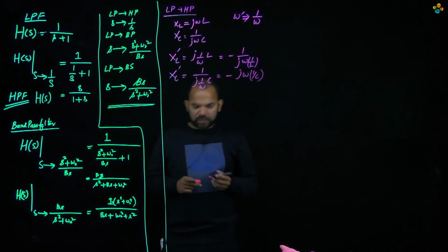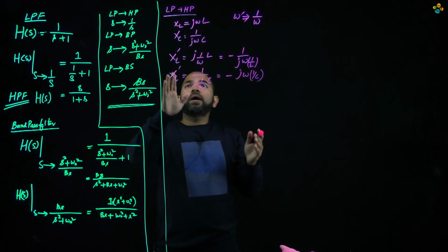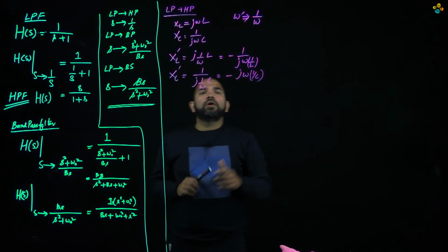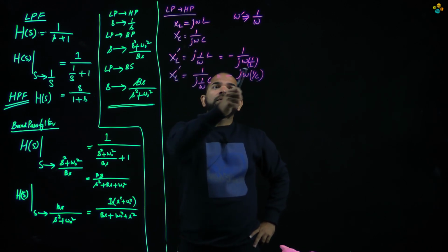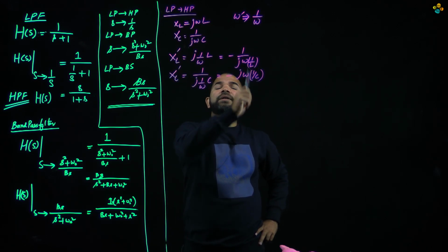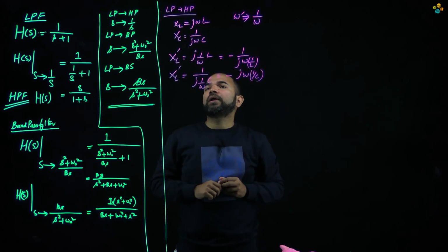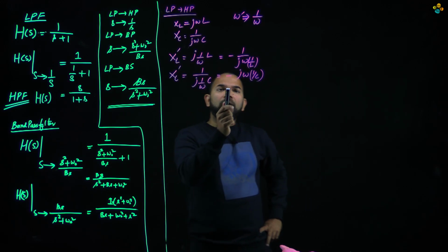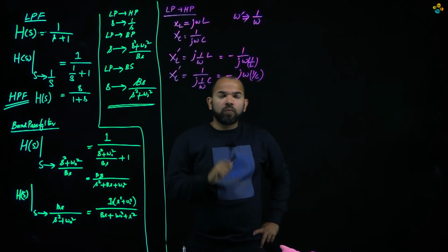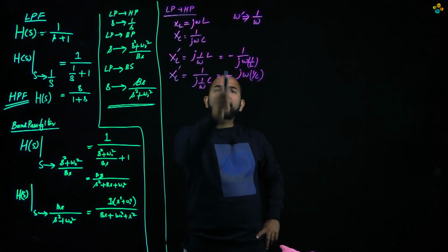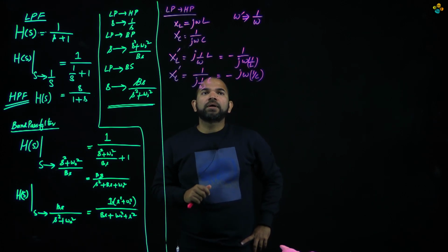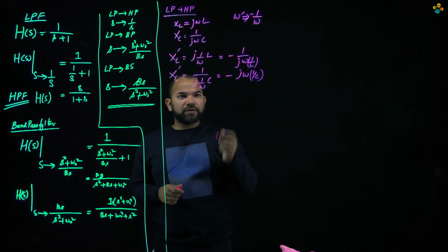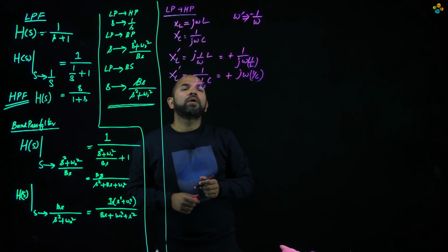So what we have seen, if we have to use this transformation, the inductance is gonna be replaced with the equivalent capacitance of 1 over L value, and the capacitance would be translated into inductance with 1 over C value, and there is one negative sign also comes with this, so we can compensate this sign and we can modify our relationship for this transformation. So both the terms would be positive.